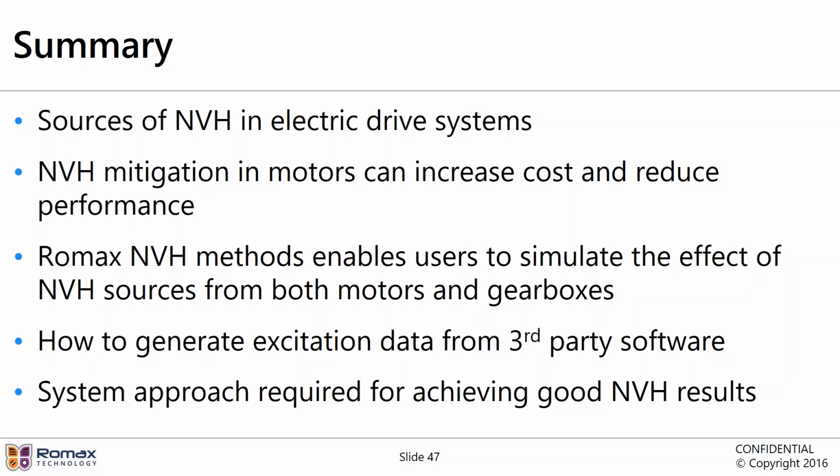A typical method is to generate excitation from a third-party electromagnetic finite element software. And in general, a system approach is required for achieving good NVH results, because an excitation from the motor can cause a vibration in the gearbox and vice versa. So it's important to see the response of the entire system rather than just the motor and gearbox in isolation.